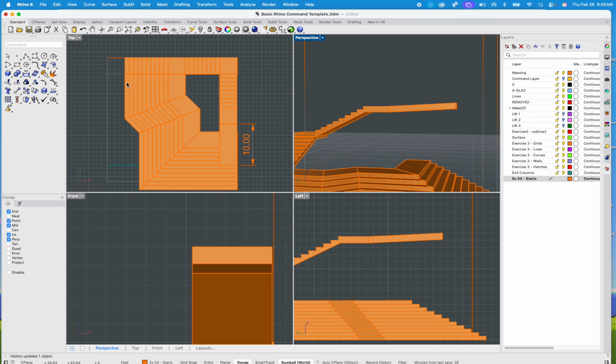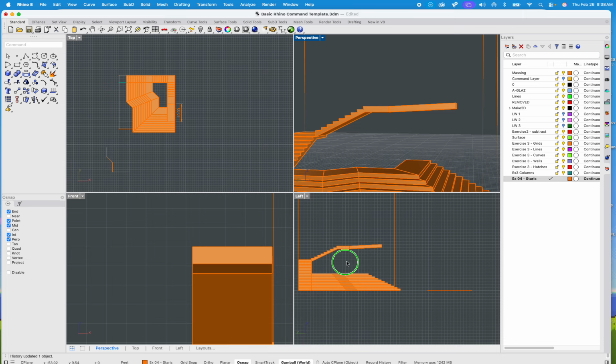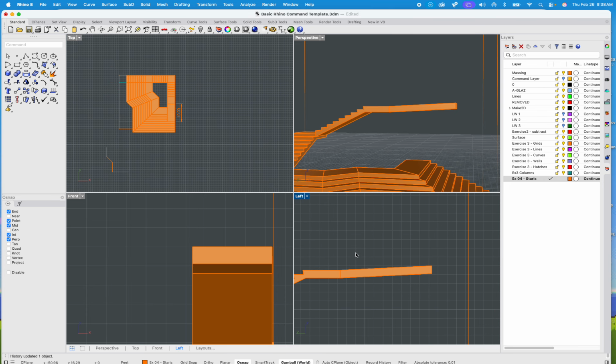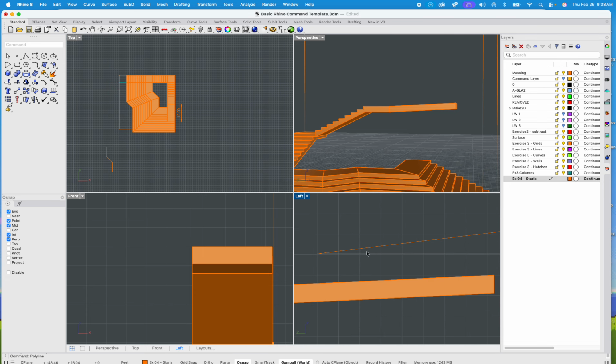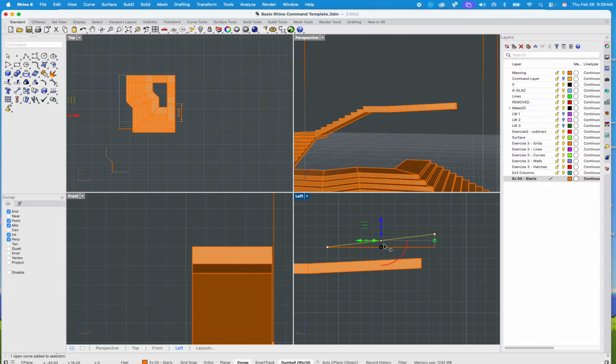But as you guessed it, we can also draw it and extrude it, right? So for instance, maybe I wanted to draw that a little bit more technical. I can get a polyline involved and quite literally draw that ramp. Right, so there's nothing wrong with extruding that, but keep in mind you're going to get a weird triangular situation. So I would have to offset that. So for instance, exploded, and as you can see, there's a lot more steps than just moving the face.